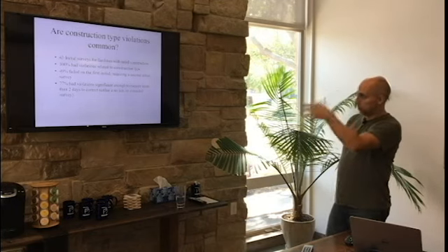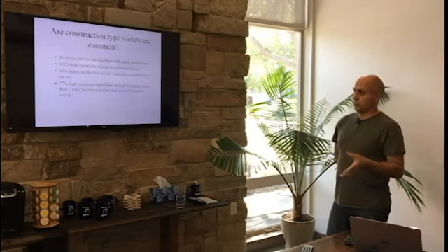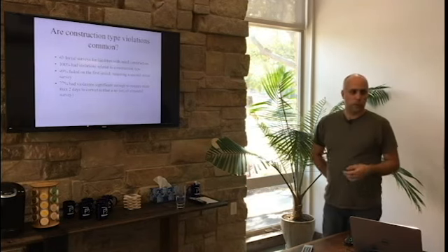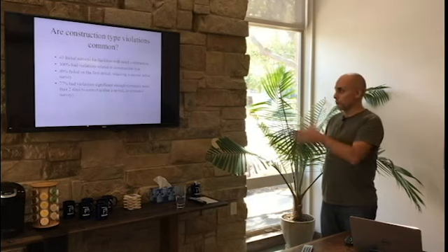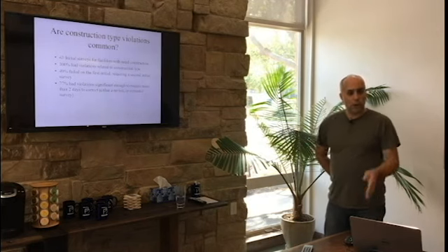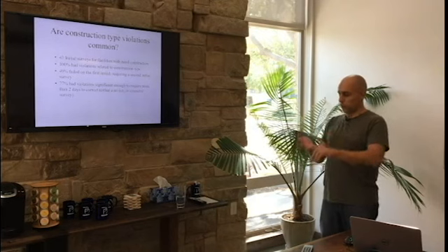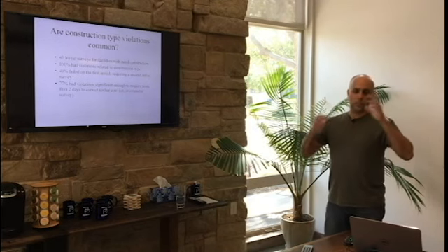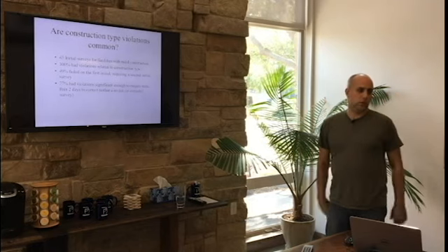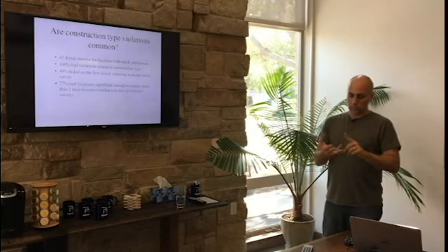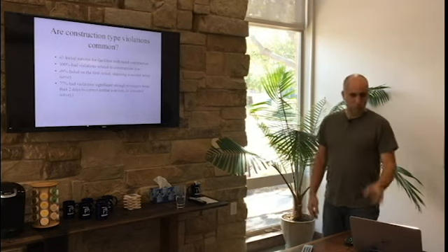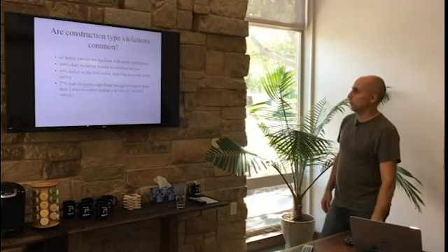And then to give you an idea, 100% had issues, 49% of this, so roughly half totally failed their first inspection due to construction-related issues. Fire-rated construction. This has nothing to do with fire alarm, fire sprinkler, has nothing to do with any of the licensing regulations. It's just rated construction issues, because they're the most expensive and most time-consuming to fix, next to emergency electrical, which can be much more expensive depending on what it is.